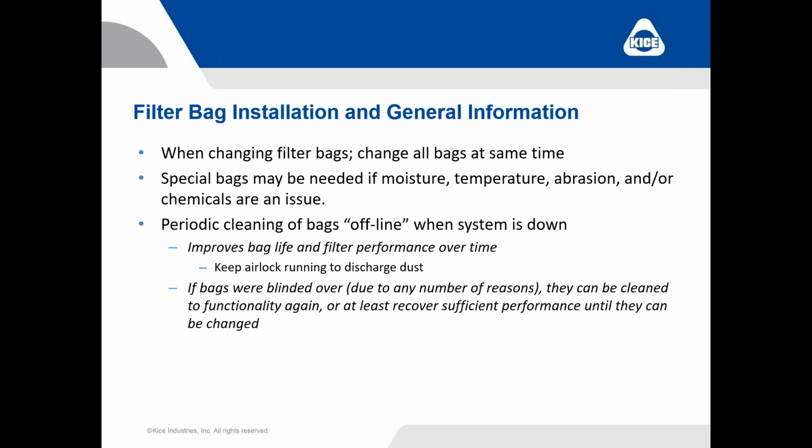For my money, for my time, if I'm going to get inside of that thing and if I'm going to get dirty, you just as well pull out all those socks, do a sock replacement, and take your filter back to new. I just think that's a much better, more efficient use of time. You're not doing yourself a whole lot of favors by just replacing one or two bags. Again, time allows for what it allows for, and sometimes that's all that we're able to do, and that's fine. You're not hurting anything, but maybe not giving yourself the biggest benefit that you can.